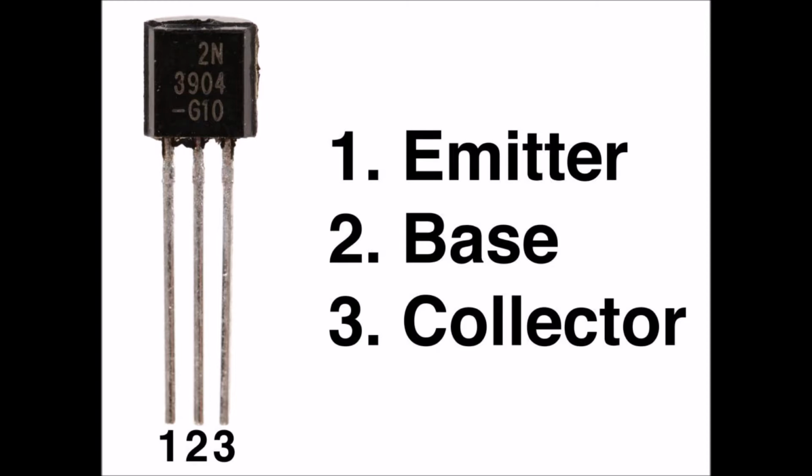Figure 22.7 shows why this effect occurs. Points X and Y represent the instantaneous current extremes during the signal cycle in this particular case. Note that the slope of the line connecting points X and Y is less than the slope of the straight line part of the curve at and near point A. When our AC signal is so strong that it drives the transistor to the extreme points X and Y, as shown in figure 22.7, a transistor amplifier introduces distortion into the signal, meaning that the output wave does not have the same shape as the input wave.